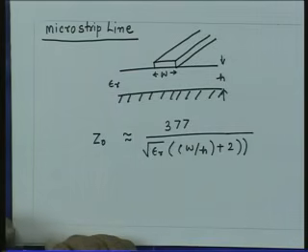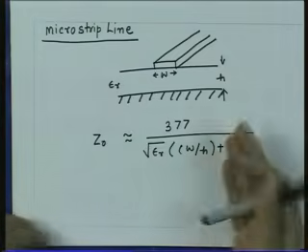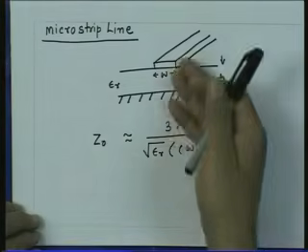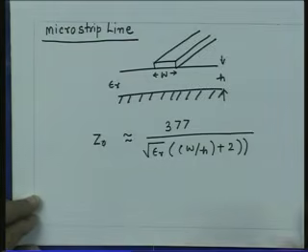But when we go to high frequencies, again we standardize the impedances either to 50 ohms if I am going to connect this structure to a coaxial cable, or I can realize the structure with higher impedances if I am going to make the connection to the parallel wire structure.